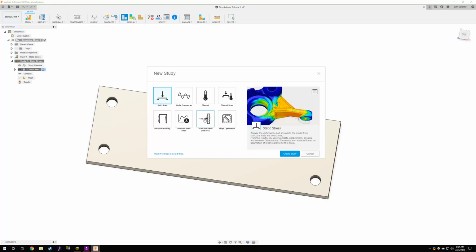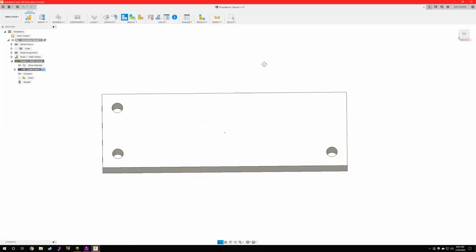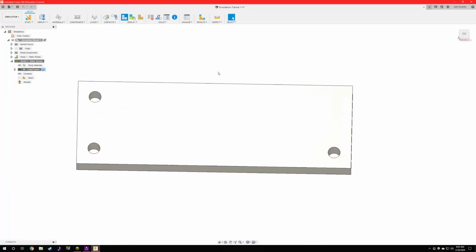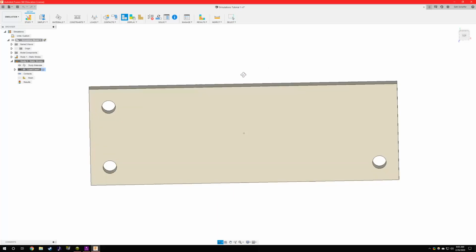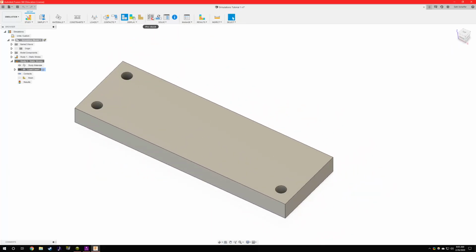Like, I have no idea how it's even in preview right now. I don't think they actually have a final release of it currently for Fusion. In SolidWorks, I don't even think that my $3,000 CAD package that I get for work has the ability to do impact simulations. So really, you're gonna wanna start with static and just use high loads to get a general sense of where the weak points of the part are and where there's weight that could be removed.